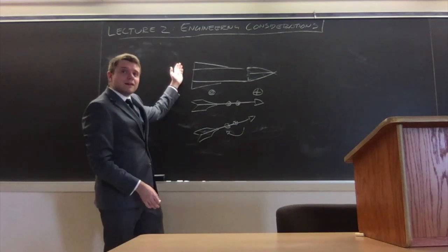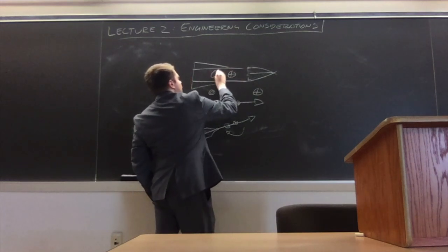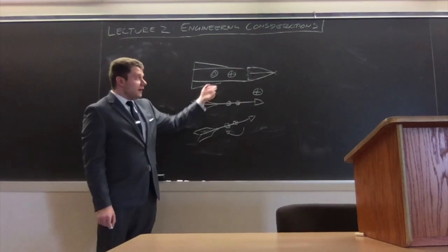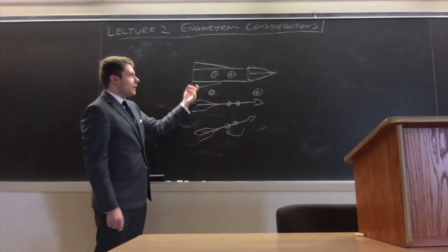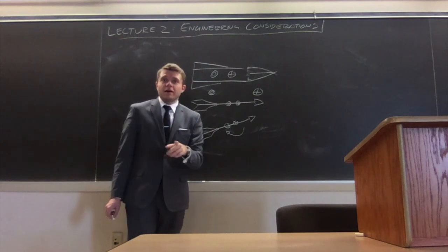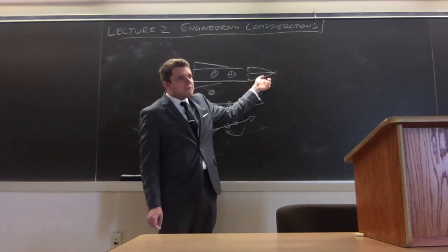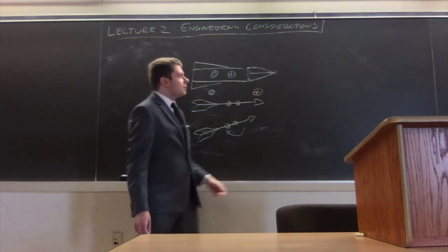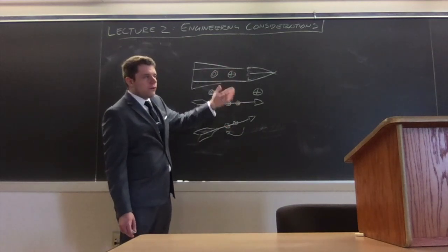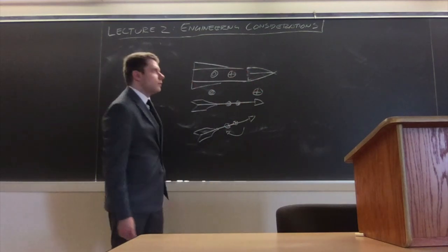The rocket's working in the exact same way. You have fins. You have a center of gravity somewhere here and a center of pressure somewhere here, and it stays stable for the exact same reasons. So rockets are designed the exact same way, very similar principles to the arrow. They have draggy surfaces at the back that keep pointing forward, and they have a little bit of mass in the front. And this seems very paradoxical. If you add more mass to a rocket, it will sometimes become more stable and go higher. It's really screwy, right? But that's aerodynamics at play. If the rocket deviates from its course very slightly, or twists or turns, or gets caught in a little bit of stiff crosswind, it'll keep pointing straight and it'll keep going about as straight as it can possibly go.